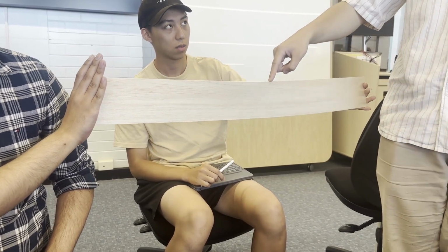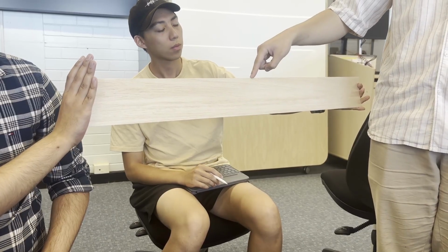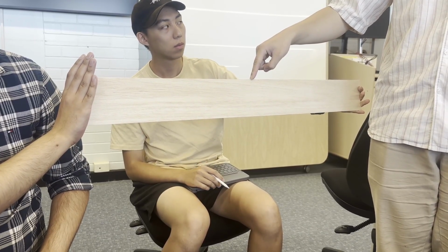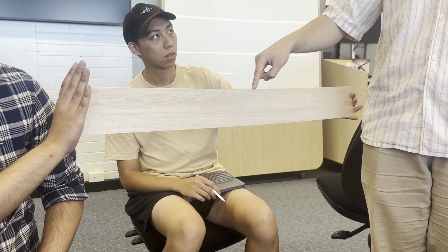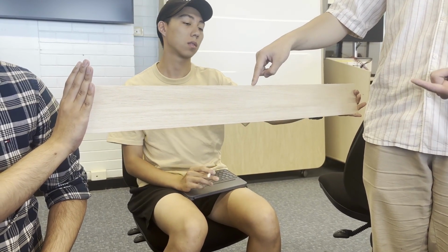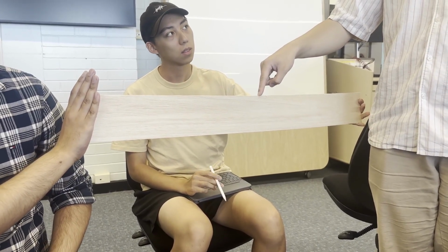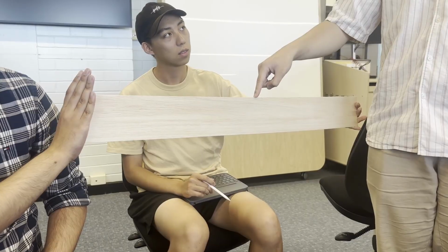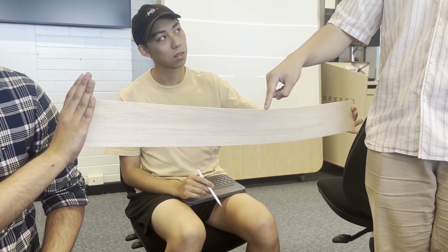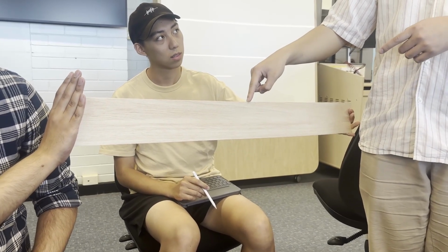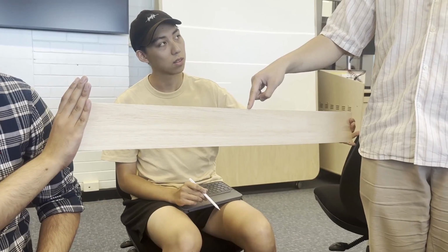So this is simply supported, and I'm putting a point load in the middle. What's happening is, which side's in tension and which is in compression? Bottom's in tension. The top is in compression. So it's an uneven distribution of tension and compression, and we know that compression causes buckling, right? So the top wants to buckle out, but the bottom wants to straighten out because it's in tension. Do you see this weird phenomenon that's happening? And this happens when there's an uneven IX versus IY, basically, right?